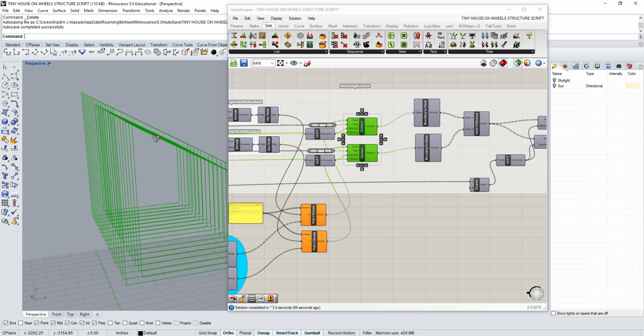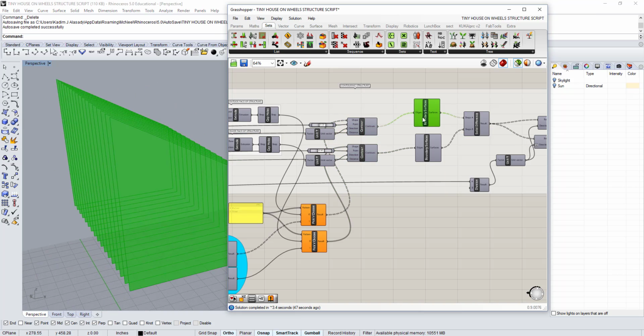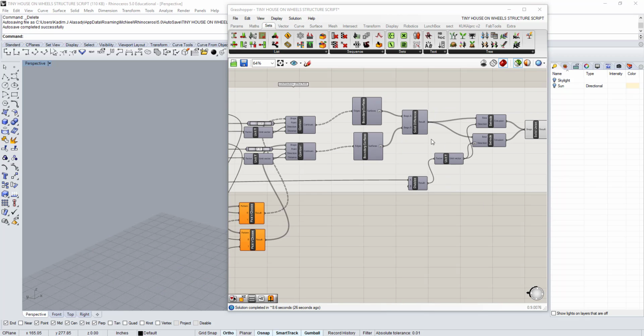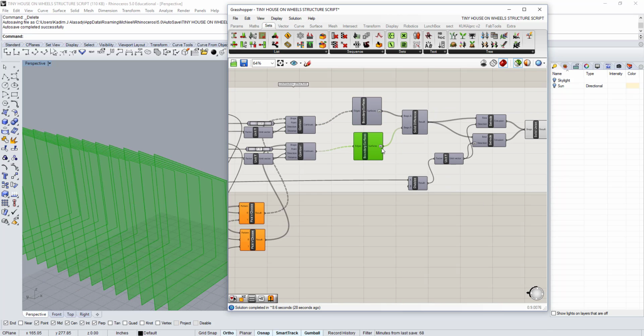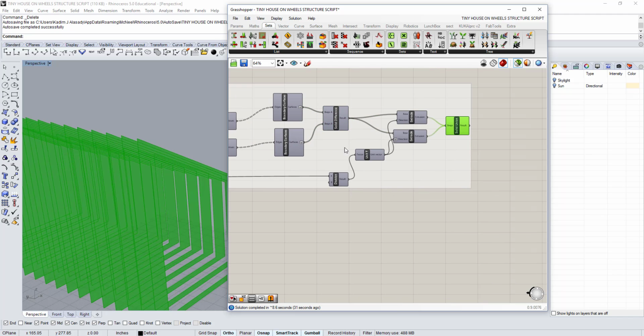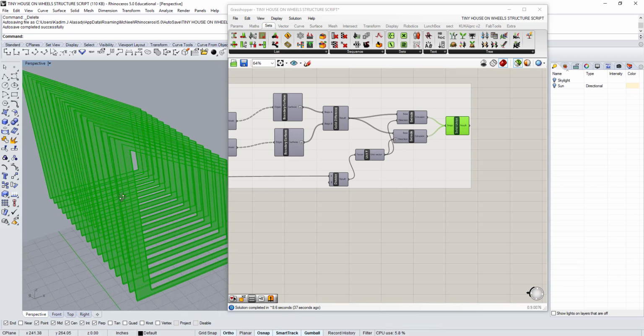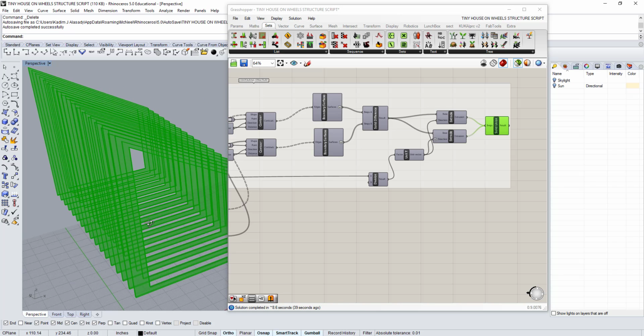So we have the two contoured curves, and then we created the boundary out of both of them, and this is supposed to be a solid difference. So let's just flatten these and see what happens. Maybe that will fix it. That's taking a while. So that did it. If you flatten both of these components, that will give us an appropriate solid difference, which would then lead to a correct extrusion. Okay, so this is great.